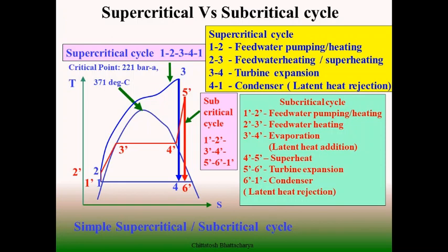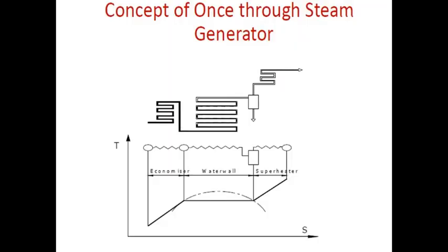Side-wise, it is not that all the supercritical units start from the supercritical regime only. All the startup operations are in the subcritical regime. So naturally there is a separating unit, a steam water separating unit, even with the subcritical, supercritical boilers. And this separating unit continues to separate the water steam mixture with a circulation between the evaporator tubes, the evaporator water walls and the downcomers.